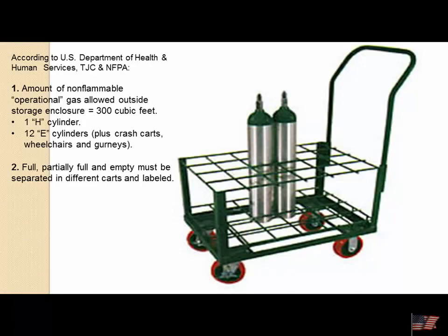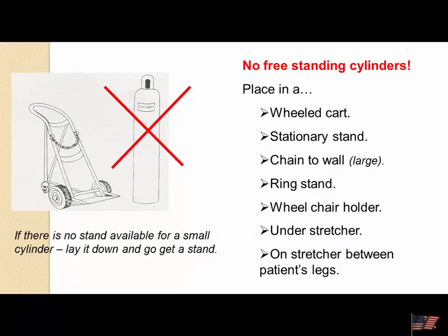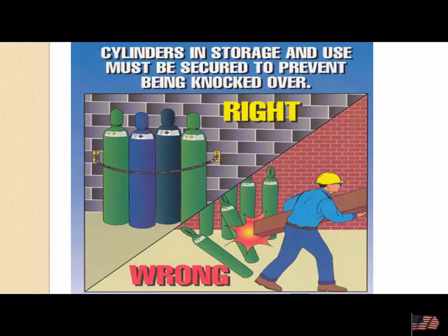And there is a ruling, again, from the NFPA, the National Fire Protection Association, that says how many cylinders you can store in a specific area. And again, never allow them to stand. If you need to, lie them down. But more often we have them either in a wheeled cart or a stationary stand. When there's a bank of cylinders, often we'll have them chained to the wall. So you don't want to have them the ability to fall over.